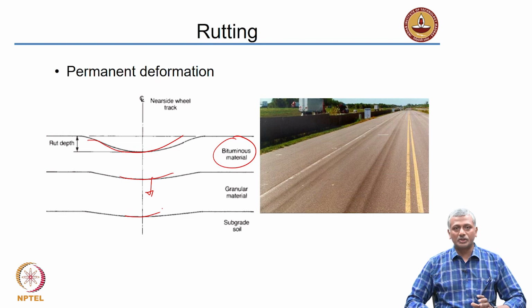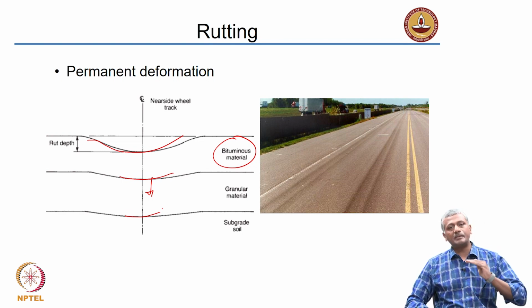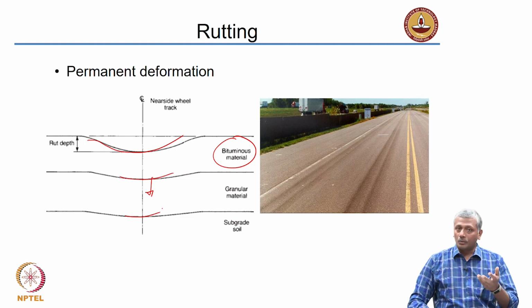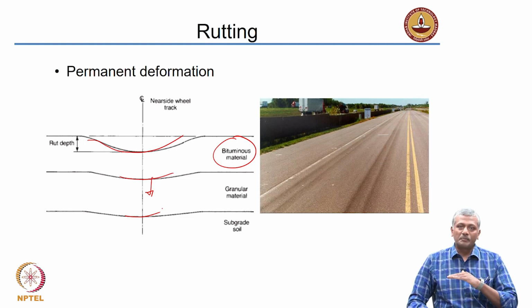Okay. So, you need to ensure that you design the highway pavements with asphalt which is able to sustain the temperatures. Now, one thing you need to understand, asphalt pavements are black. So, in the daytime they are going to absorb more and more heat radiation. As they absorb more heat, the temperature on the road surface will be certainly much higher than the ambient conditions.